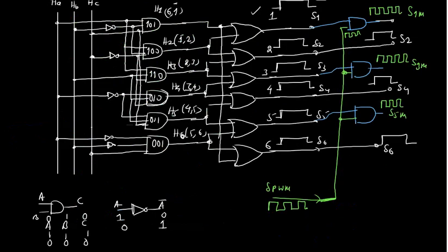Earlier you were giving delta PWM because of current control. Now you are going to give the delta PWM because of speed control. Clear? This part, selection of the switches and modulation, will always remain the same. So this module is called switch selection and modulation. This whole arrangement is called switch selection and modulation, or you can say gate pulse generation.